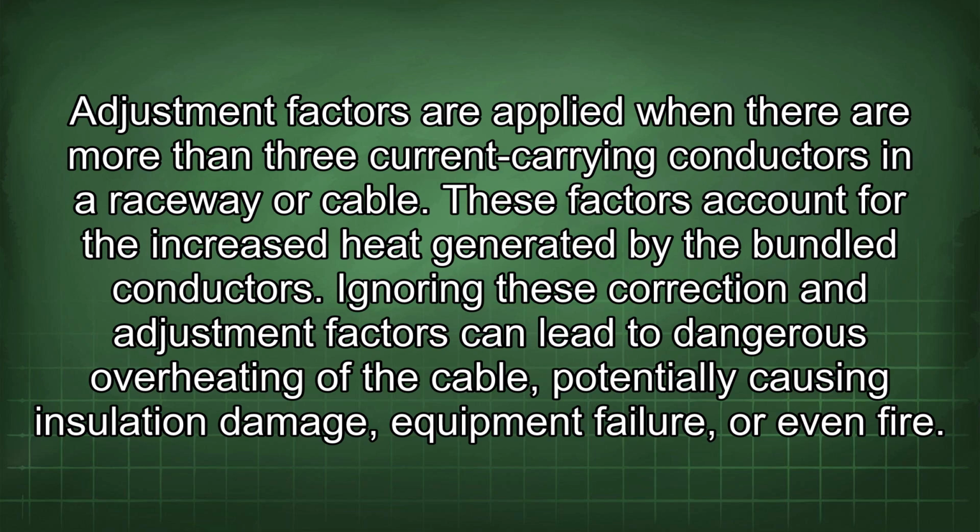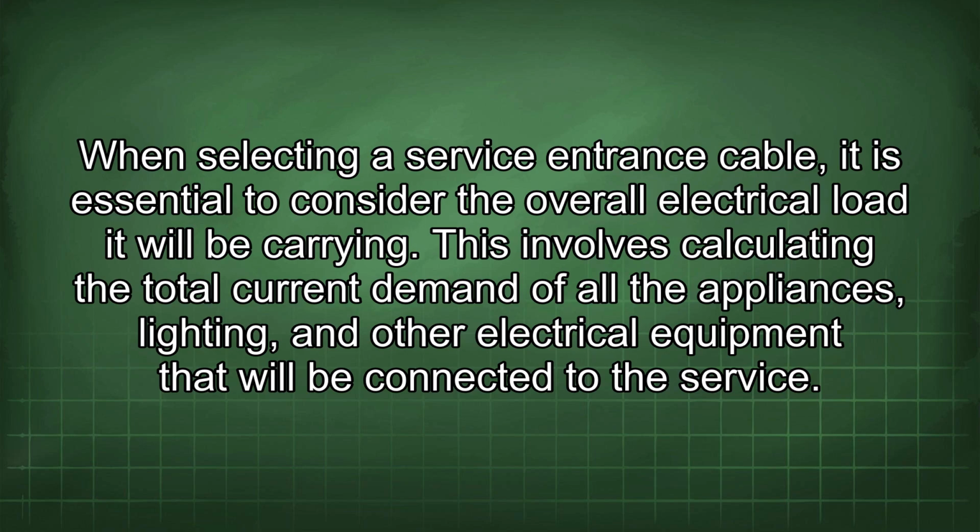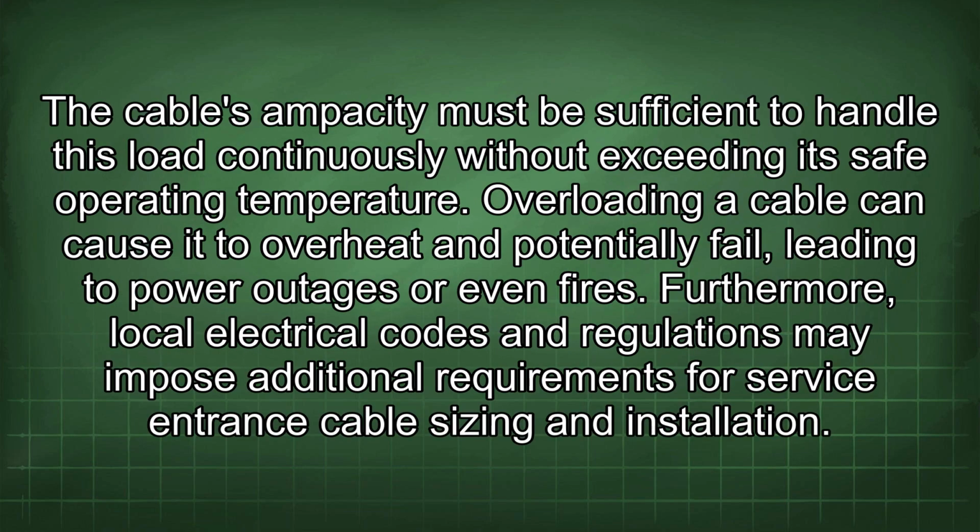When selecting a service entrance cable, it is essential to consider the overall electrical load it will be carrying. This involves calculating the total current demand of all the appliances, lighting, and other electrical equipment that will be connected to the service. The cable's ampacity must be sufficient to handle this load continuously without exceeding its safe operating temperature. Overloading a cable can cause it to overheat and potentially fail, leading to power outages or even fires.